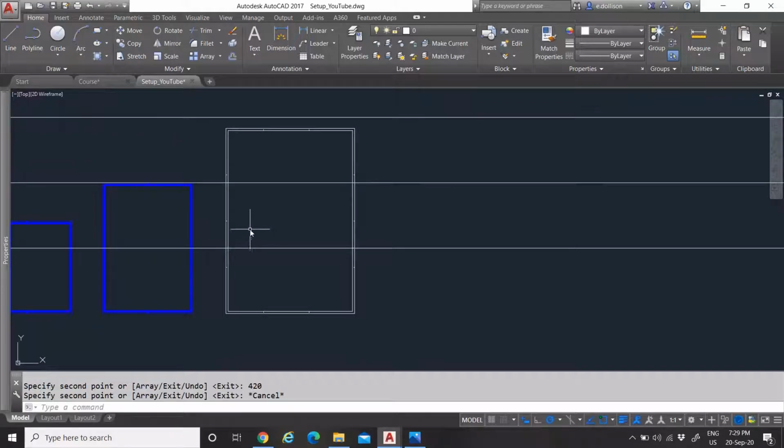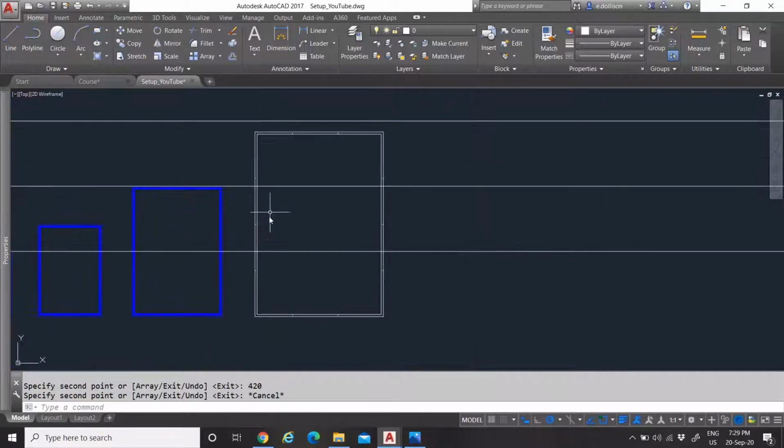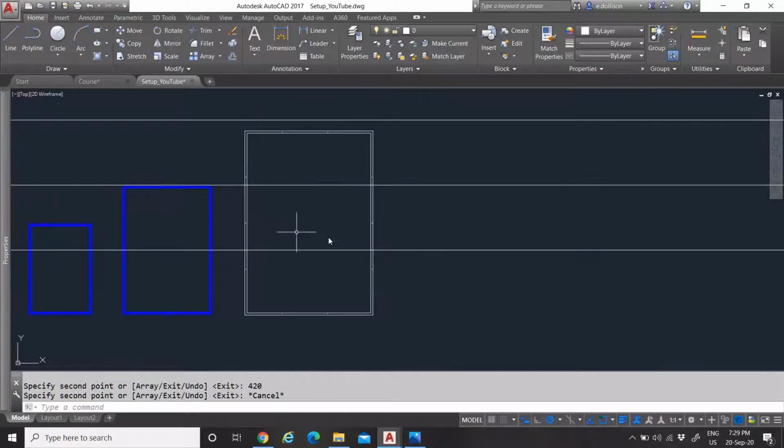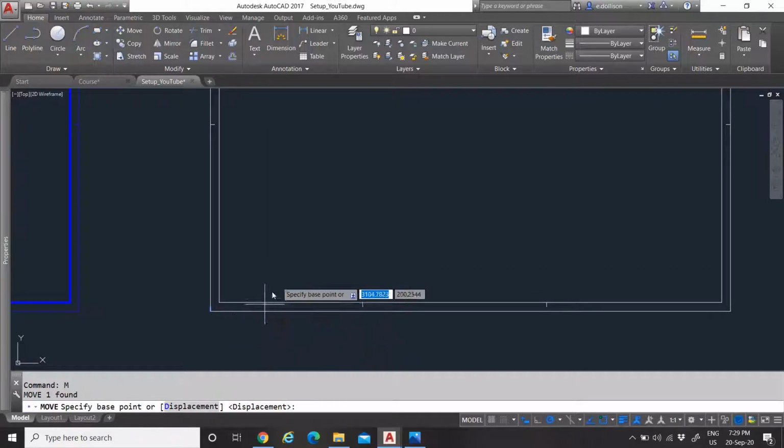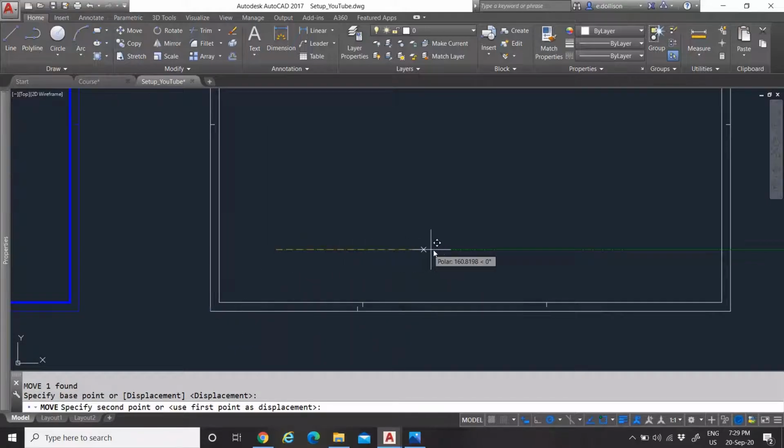So here we can see that our paper in our landscape view will be folded 3 times, so then you would have 4 sides. And also this way, it will also be folded, of course. So we draw our line 5 millimeters, enter, select, M for move, space, click anywhere on your screen, and then displace your line to 297.